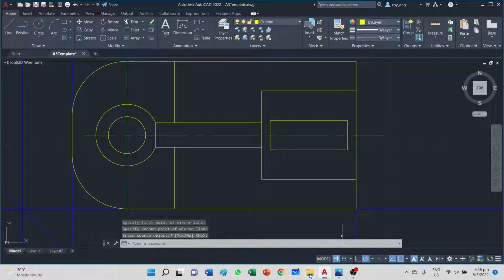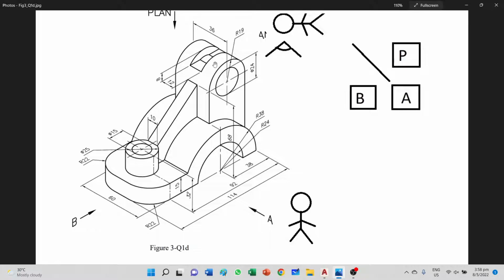However, if you were to look at the drawing closely, there are outlines drawn over here. And how is that so? It's because you made a really deep cut, and the cut was so deep that it starts to expose the hole that is running through this lug. It starts to expose here. So when you look down, there is no material here at all. In fact, this top part here is actually a hole. If you were to put a shaft in, you will be able to see the shaft, and when you put your finger in this little hole, you will be able to feel the shaft. So therefore there are outlines there.